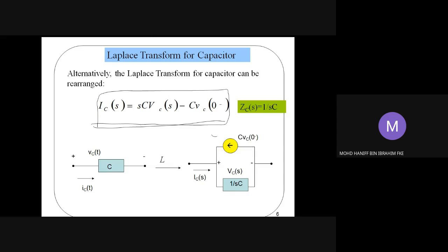Okay, right. So from this equation, that should be the transformation of the circuit from time domain to the frequency domain, in which we can say that the capacitor's current actually consists of two components or two branches. The first one is the current flowing through the capacitor, which is sC V_C(s). And the second component is the current source, which is C v_0(0-).